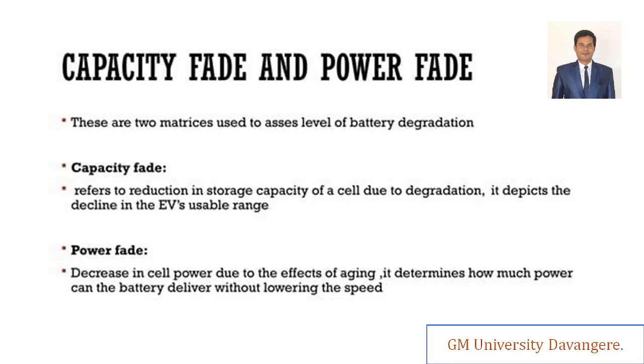The battery has to deliver that much power to generate that amount of torque, right? That's why it is not giving the maximum power, and it will not gain that much current either. That results in poor acceleration, and poor acceleration in hill climbing also. That would be the reason. That makes a lot of impact for EVs also, right?